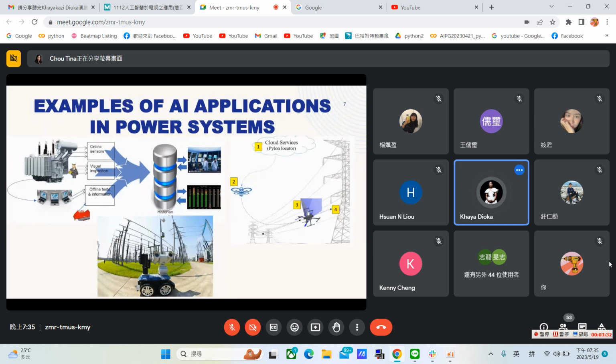We've got a problem. This line is actually arcing. We've got a problem there, but that line hasn't gone off. Now, how can you repair it? Take it out quickly, or you can even do live line work on that same line. But you've got enough information to determine what is the next step and the quickest step to restore system stability before you've got more catastrophic failures within the network.